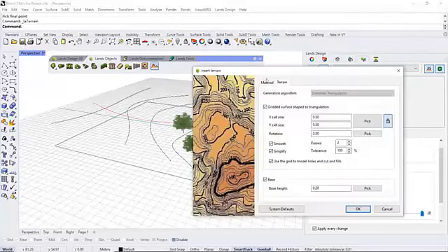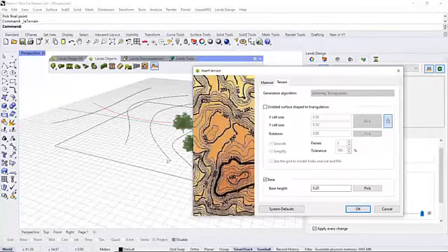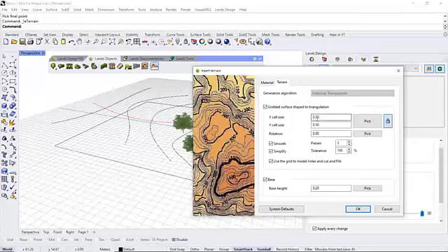So we run it. We can use a pure Delaunay triangulation based on the control points of these curves that we'll use as input data for the terrain, or we can actually use this grid surface shape triangulation that will let us have control of the cell size and therefore generate a terrain more or less accurate according to this input data, the initial contours.